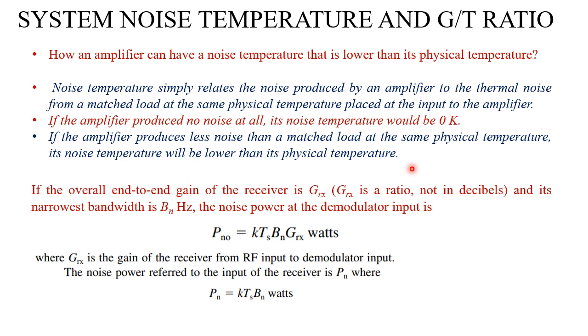Got it? So that is why the noise temperature becomes much lower compared to the physical temperature, because it is not exactly the actual temperature. You cannot measure this noise temperature with the help of a thermometer. It is not like that. It is a way of representing the noise power. Get it? We are representing noise power in terms of temperature, right?